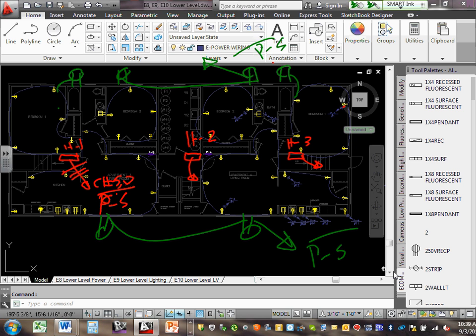Can I get your attention one more time? For the common area, please drop a receptacle at every landing. Here you go, Adam. Right here, here's one landing. I want a common receptacle here. Here's another landing here. I want a common receptacle. Every landing, drop a receptacle. In the lower level, we have 2 landings. There's one landing here. I want another common receptacle here.